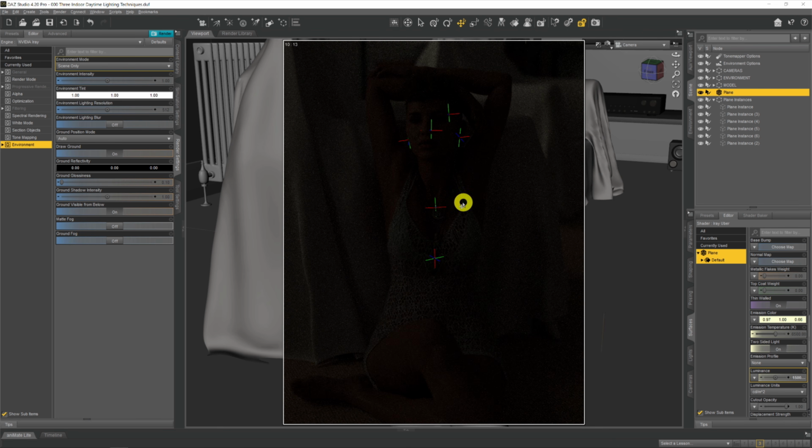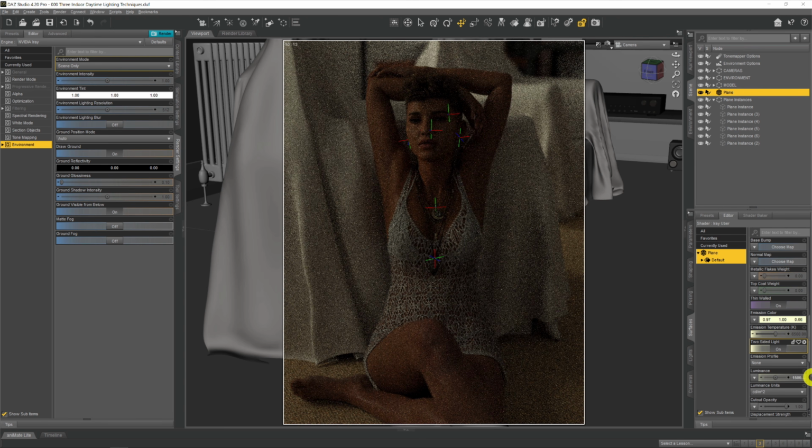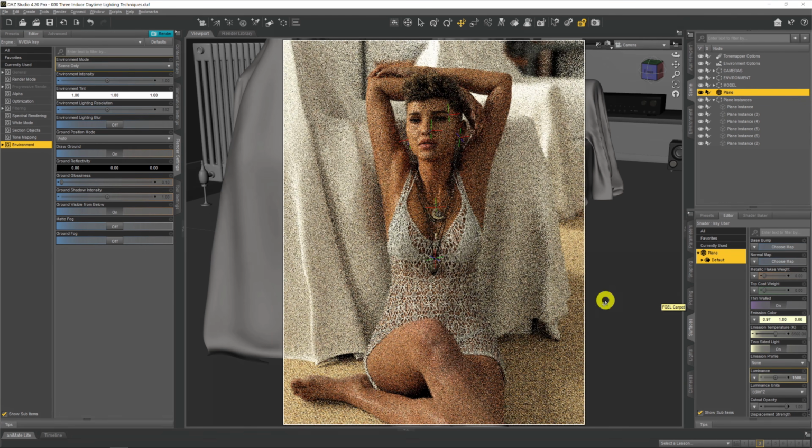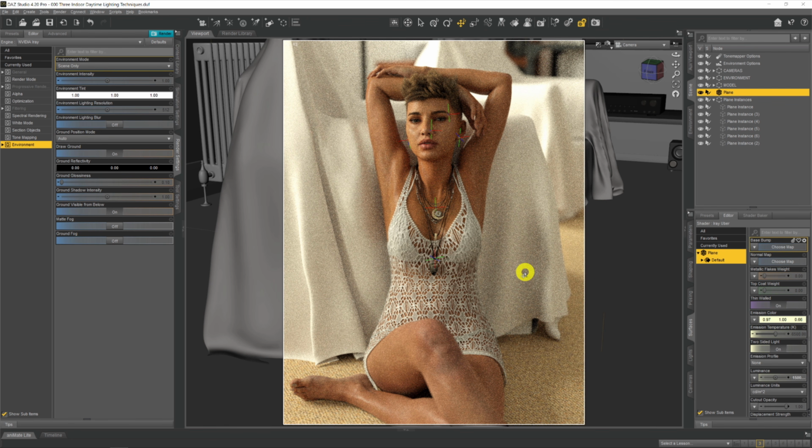So now it's a fairly dim image still, but we can at least make out some more details. We'll step up again just to bring a bit more brightness, and again probably one more needs to be done. Add another 0 on there. And you can see now our model is fully lit up. All of those instances that are down here are copying this one that we're actually changing in the surface settings here, and it's created a fairly acceptable daylight, sunny, lighting in the room, and all just by changing that one emissive light that we set up, and all the instances are just following suit.